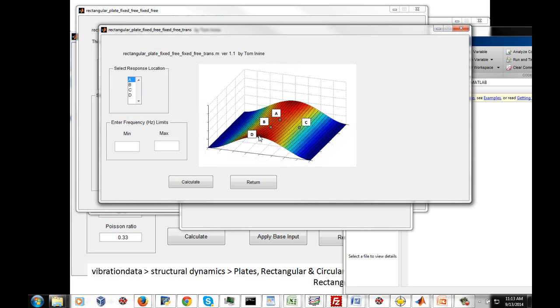It's kind of on this lip here. This is going to curl upward in terms of how we're representing the mode shape. So let's go from 10 to say 2,000 hertz for our frequency, and let's do point D there. Let's calculate what our transmissibilities will be.